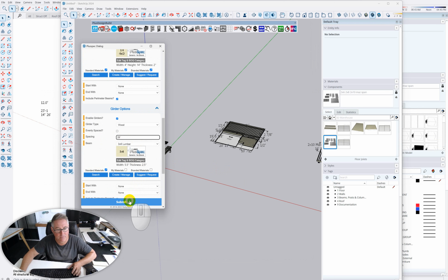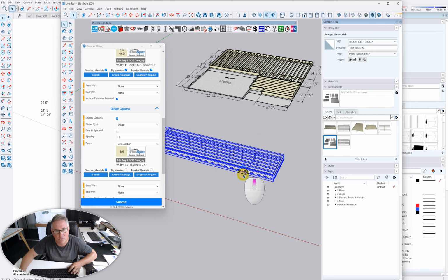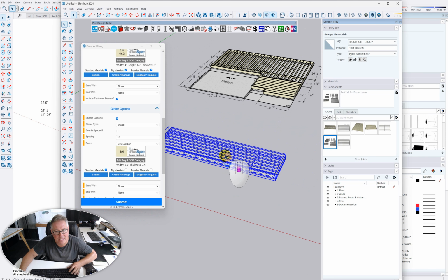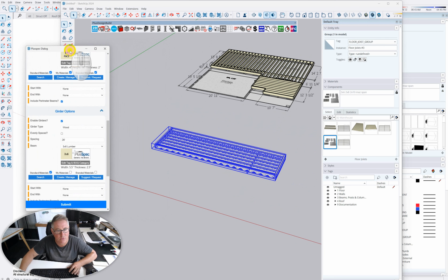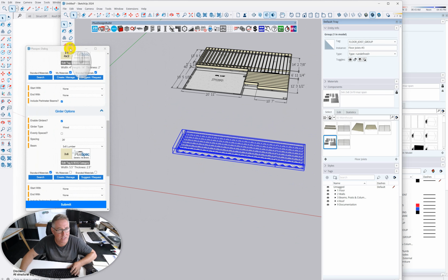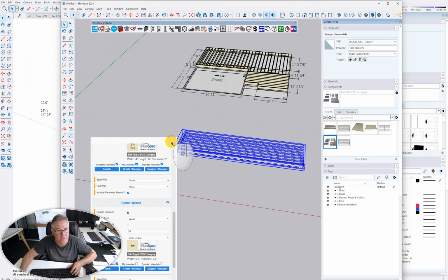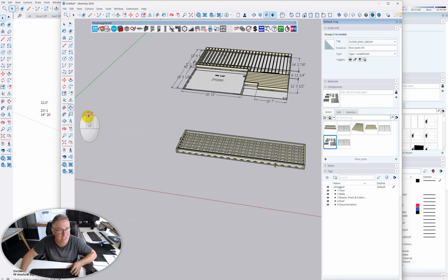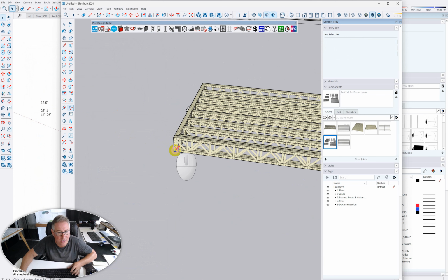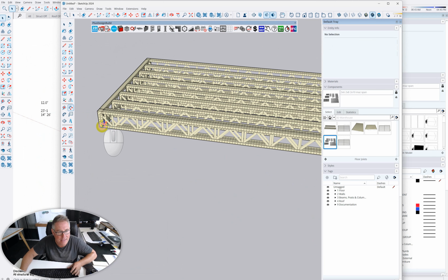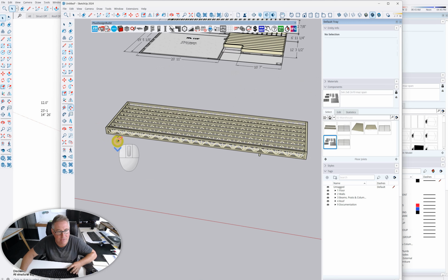and go submit. Now what I'm going to do is draw just a joist out in the middle of nowhere here, and I'm going to come back this way. Right, and you'll notice that it's spaced that girder for me. Let's move this over to here, and I'm going to dimension it. I'll close that for a second. Dimension, it's in the large tool set, guys. I've created a keyboard shortcut, which is D. Let's see if I can get this to click on there.